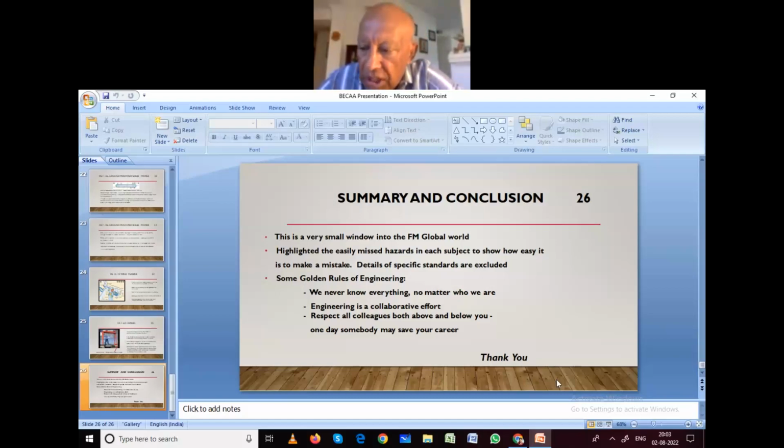Those protection criteria are spelled out in Data Sheet 3-26, which I quoted in my presentation, and it is available to you from the FM Global website. Download it and take a look. Fires will be there, but the objective of the protection system is to reduce the intensity of the fire to such an extent that it becomes a non-event. Instead of a building burning up, there will be one sprinkler head operating in one room extinguishing the fire. That will save lives, property, everything. This is what we have been selling for 187 years at FM Global, and we have been very successful.